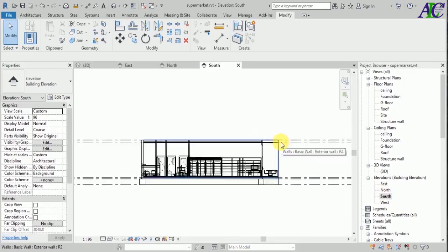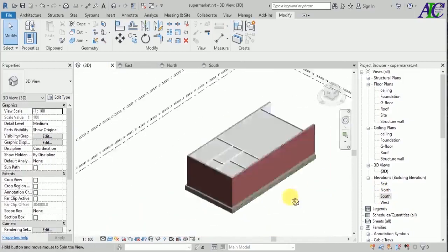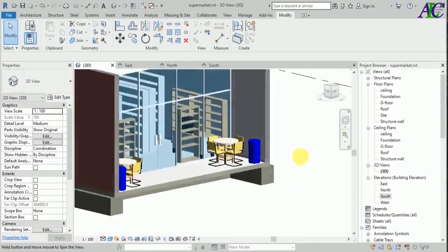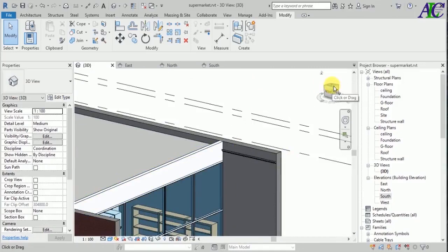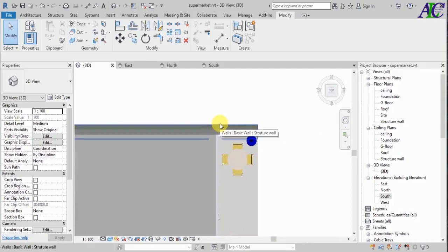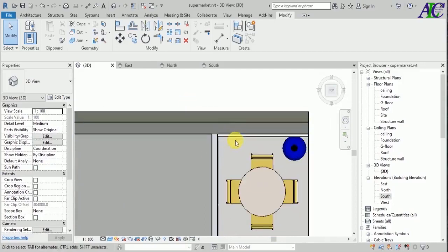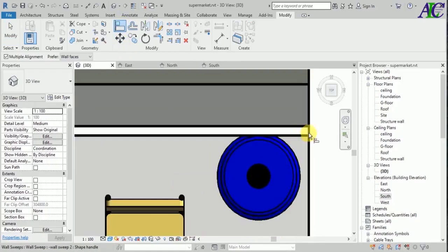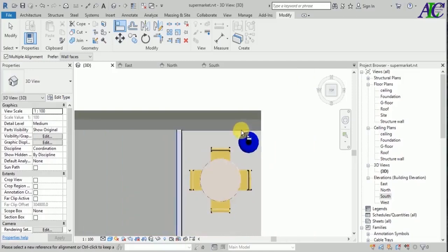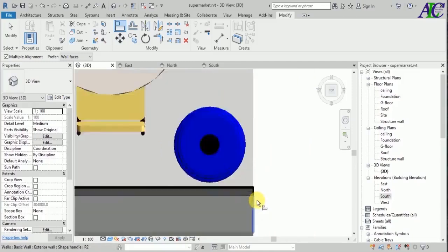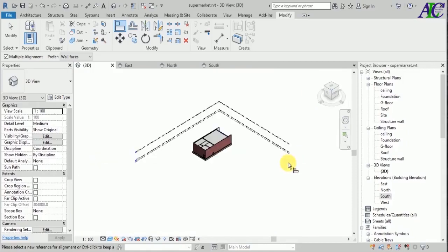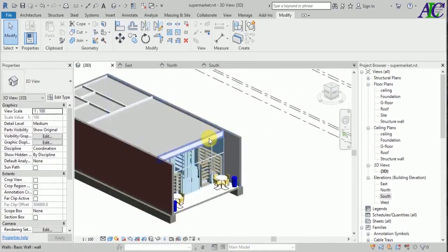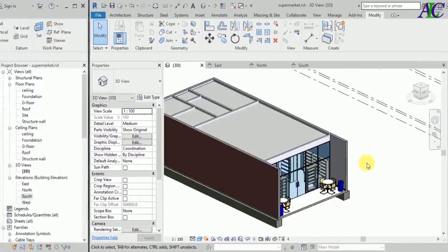Let's go to south elevation. Let's check in here. I think everything is fine. Okay, this is the shape on the floor, and this one is under the ceiling. Okay, so I don't need it in here, so I think I have to delete this one or cut. Maybe I use align tool, align from this inside the door, inside the wall. Okay, if you can find this line, you can use the tab key, then the selection tool will change. Okay, now the sweep is finished,